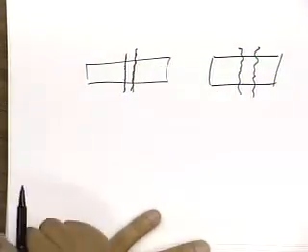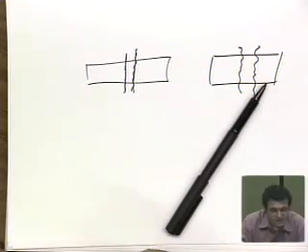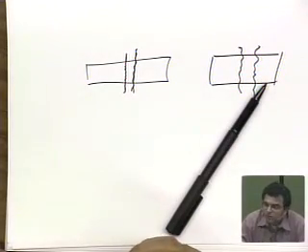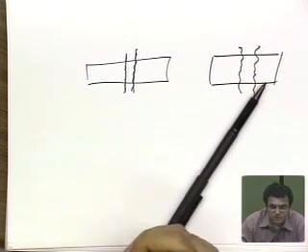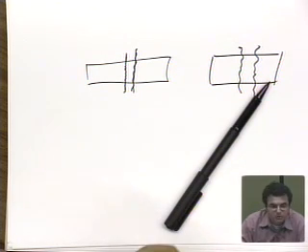It's so small. Digital technology today, for the first time, is getting to the point where you have to worry about these kinds of variations. If you're going to design a megabit of memory and you want a good yield out of that memory, you better worry about matching issues. Process variation.